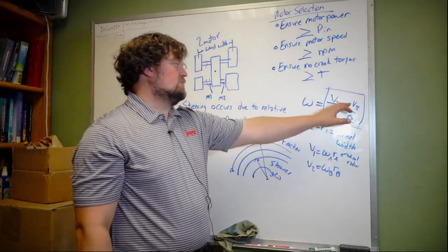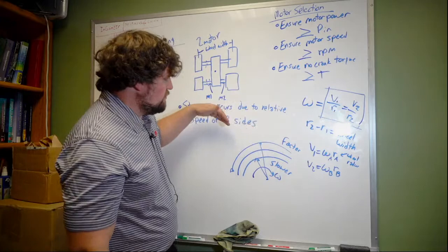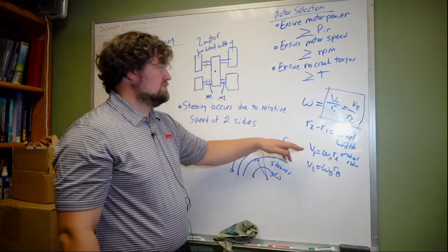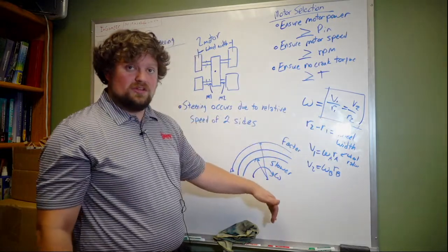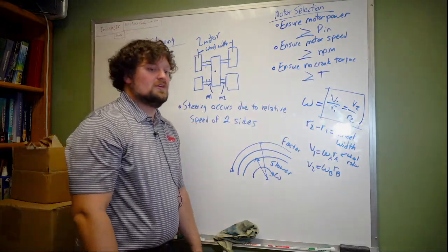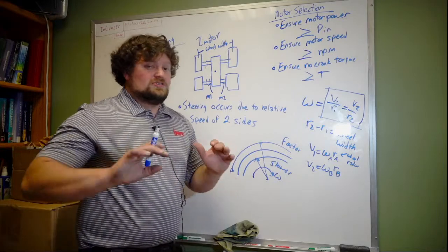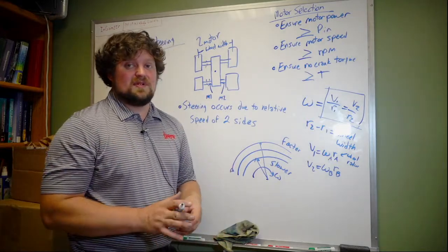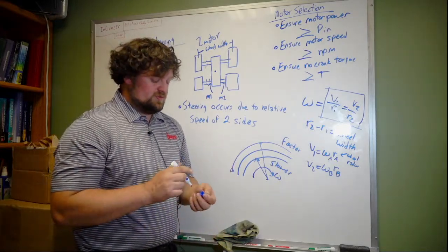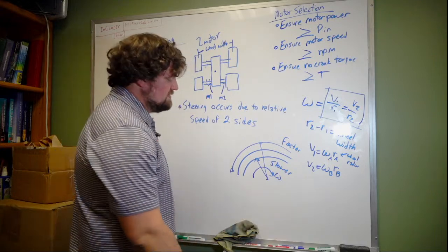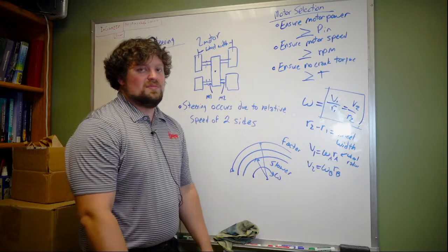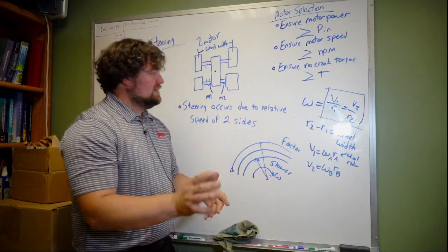The velocity of one wheel over the radius to the center of the curve is equal to the velocity of the other motor divided by the radius from that wheel to the center of the same curve. So, kind of a lot of information. Please feel free to respond with questions, but hopefully this gives you some of the math behind how to control the steering.